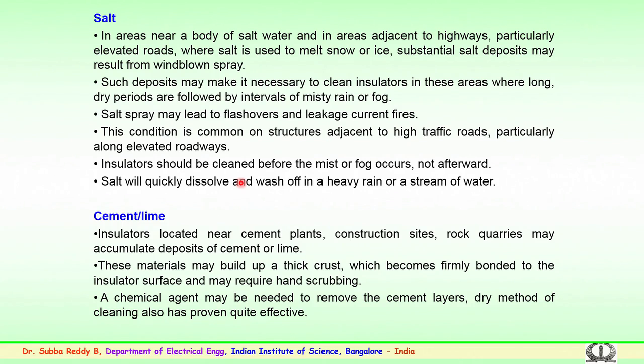Substantial salt deposits may result from wind blowing, which gets sprayed on the insulator surface. So, in desert areas, near the sea coast or near highway junctions, such deposits carried by the wind may make it necessary to clean these areas where long dry periods are followed by intervals of misty rain or fog. So, salt spray could lead to flashover and leakage current fires.